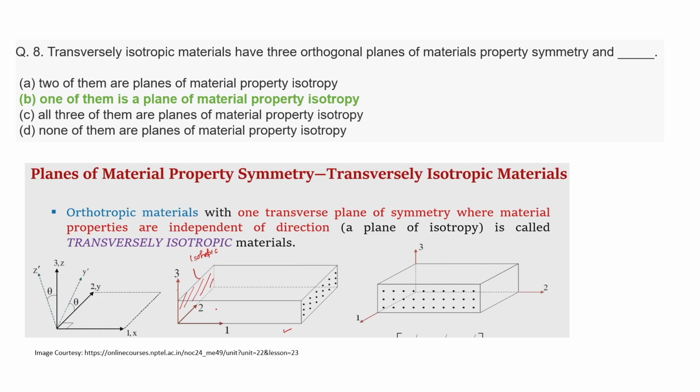As you can see, this is an orthotropic material. In this, in all the directions the properties will be the same, and one of the planes here, this plane between axis 3 and 2, is isotropic. So any properties in the direction of 3 will have the same value as the properties in direction 2. Suppose the independent constant we take is 3, 1.